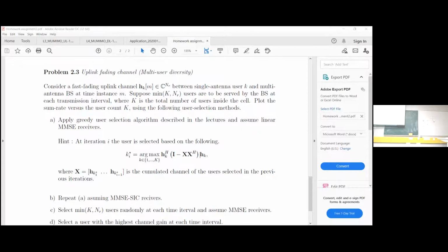Okay, so we can now express the downlink dirty paper coding SINR such that, given this encoding order, right? This only applies for this encoding order. We have the desired signal, noise, and interference from user indices that are smaller than K. If the encoding order is the other way around, then the interference would be from user indices larger than K. Is it clear? It just depends on the encoding order.